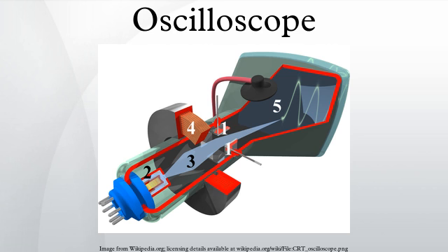The trigger section controls the start event of the sweep. The trigger can be set to automatically restart after each sweep or it can be configured to respond to an internal or external event. The principal controls of this section will be the source and coupling selector switches. An external trigger input and level adjustment will also be included.